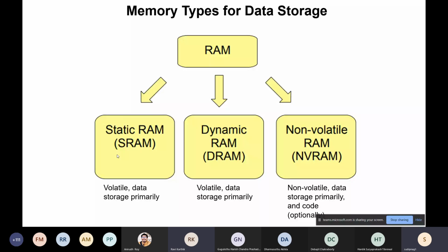Then why doesn't the refresh operation come in SRAM? Because in the architecture, it's like a flip-flop. SRAM is like a D flip-flop, you can say. Whenever you store something through the D flip-flop by applying D and clock, what is a D flip-flop? You apply 1 to D and then a clock signal, and your output Q will be updated with 1. And if your clock becomes 0, the D flip-flop will still keep that logic 1 at the output Q, right? So a D flip-flop is like SRAM, or SRAM is like a D flip-flop, you can say. But circuit-wise, the architecture is slightly different because of certain reasons.